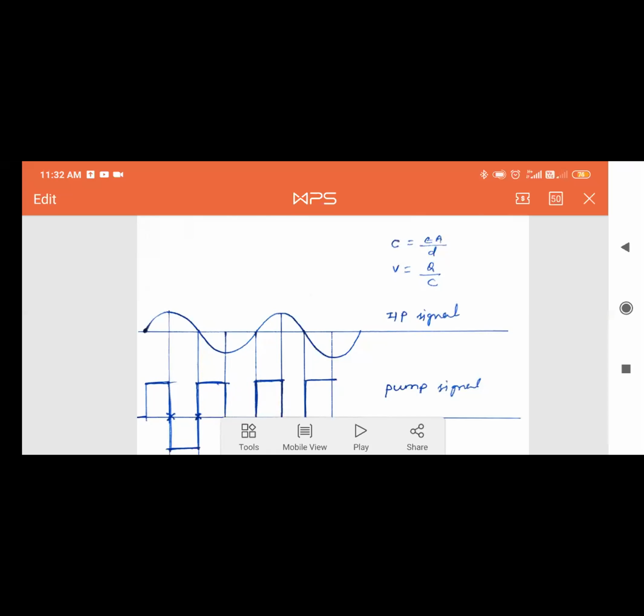Here, already we have gone through the variable capacitor, the varactor. The varactor concept is used here. It was discussed that by applying a certain reverse bias potential across a diode, the depletion width can be controlled. That depletion width is nothing but your D. So if you can vary D, then the capacitance can be changed, and if the capacitance changes, then the reactance can be changed. There it was a variable capacitor, but here this concept we are going to use for the amplification of the signal.